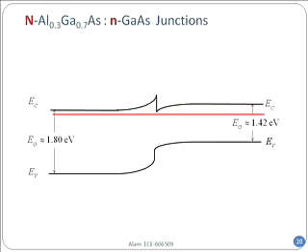Now, heterojunction transistors also allow you to do isotype. Isotype meaning N and N. You know, previously in silicon, if you had N and N, that wouldn't be very interesting, right? It's a sort of uniformly doped material. Now, if you had a little bit of doping change, maybe there's a slight variation, not too much. But for a heterojunction transistor, even the isotype, meaning both sides N, could be interesting.